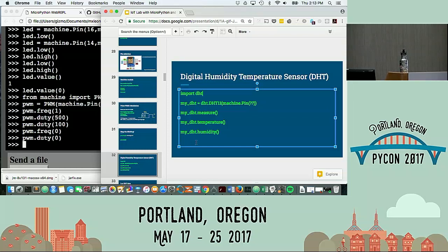And you can look and see if you put it on D5. But here, why are we moving it? Because GPIO 16 does not support PWM. It's not a function that pin supports. Okay, so I move it down, and then only this green part I need to move down, right? Just the top part of it. Yeah. Okay, thank you.